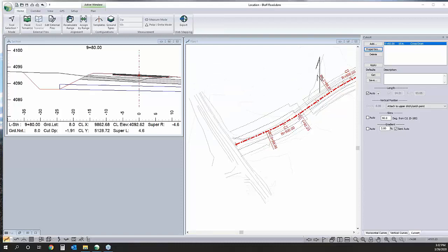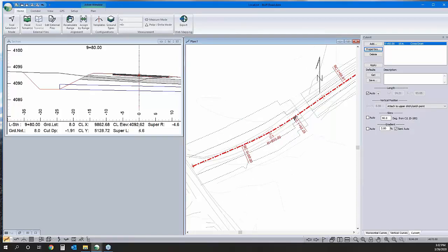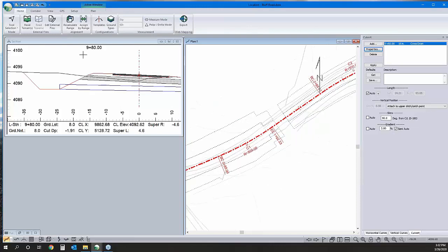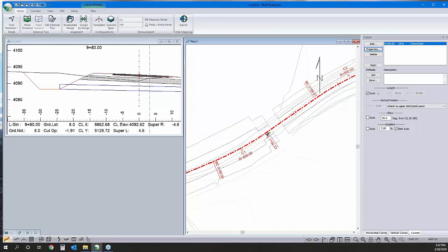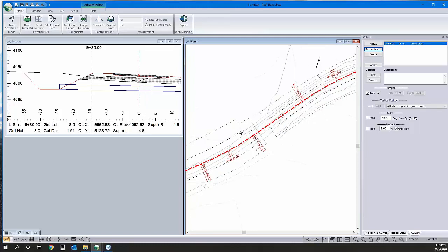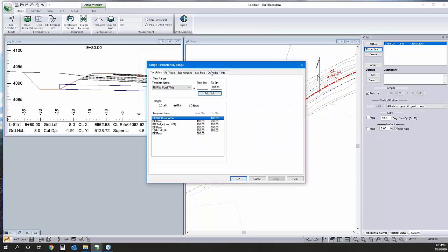Now what else do we have here? So I got a question about showing a taper up to a bridge template. Yeah, I got around that by just switching it out. Some of you may have noticed the warning I had there. So you can do the taper a couple different ways with a bridge template. Honestly, for tapers, if you're tapering your road width, 90% of the time I prefer to use my overrides.